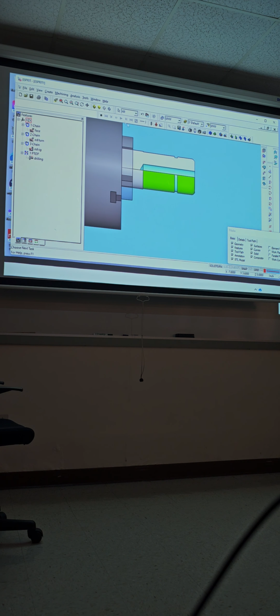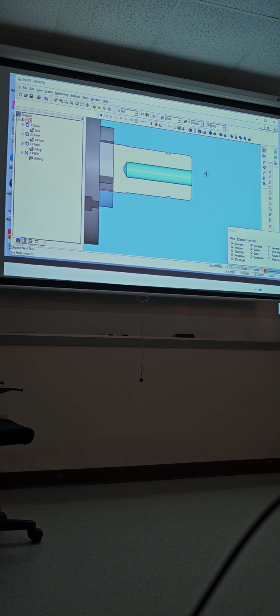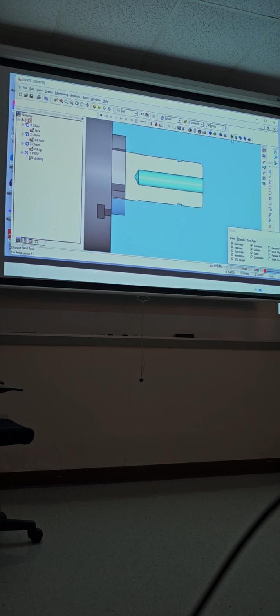So now with drilling, I'm gonna go over here. I think this is what you, Paul, were asking. Over here, you got half section. This right here. So now I'm gonna be working ID right here, half section right here. Half section. And why did I do half section? So I can see the cutaway, so I can see if those tools are clearing inside.